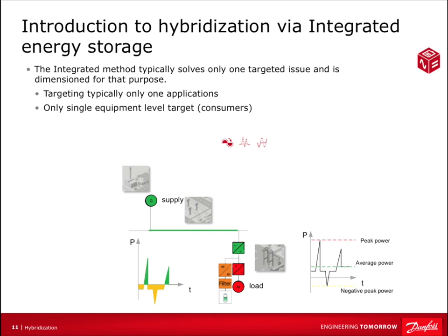For example, if I want to raise the load on the RTG, I'm going to have a very high peak current momentarily that the genset may not be able to supply. And I'm going to have an opportunity when we're lowering the load, I'll have excess energy, in which case I can then charge the battery. There is a slight difference in the hardware topology compared to the centralized situation.